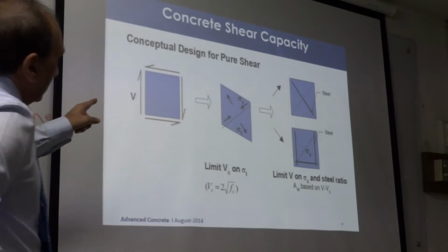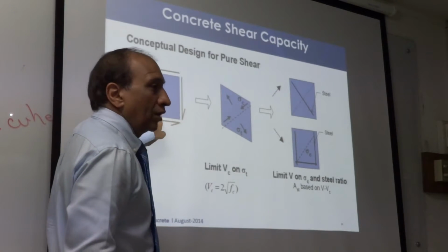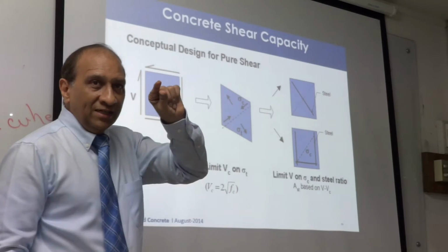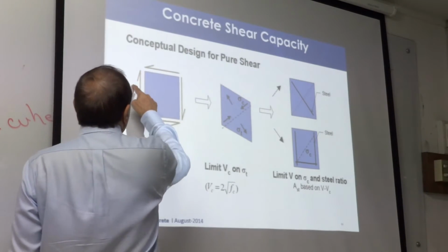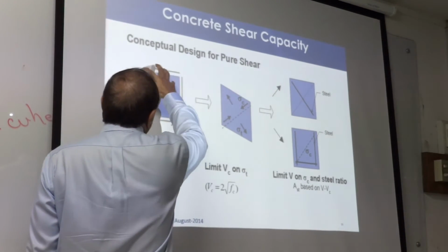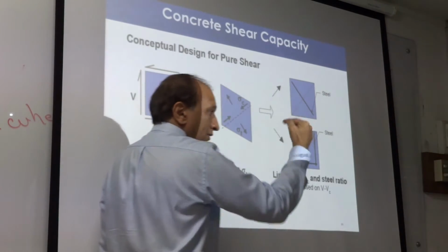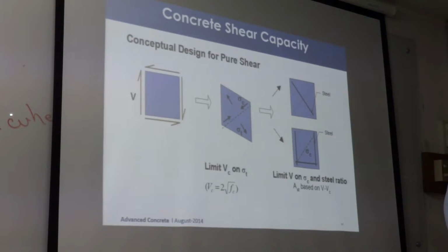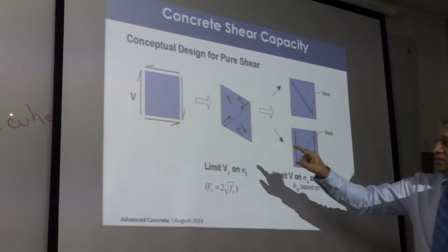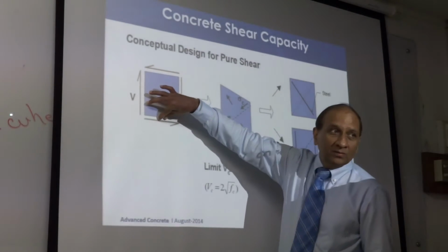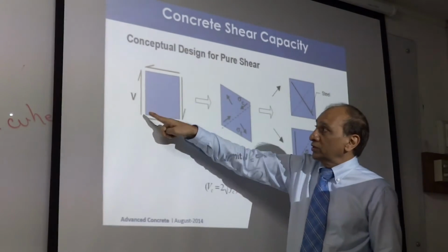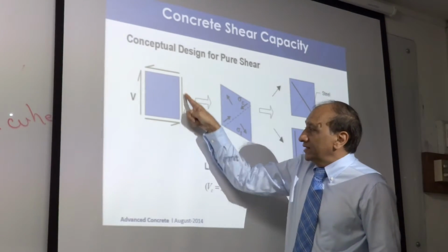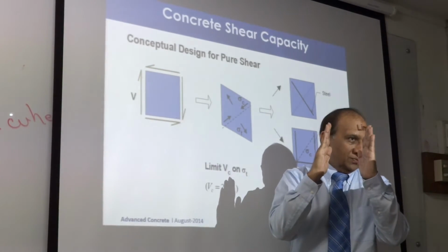Now, let's take one of those points on that section, on the beam that I showed you. One element on that section, and you will see that this is a shear. So shear must always be like this, on one element on the side of the beam, not on the section, but side of the beam, on the very small slice that we talked about. This width is very small, nearly 0 at the section. So the stresses exist like this, and shear stresses, this one and this one on the two sides you just saw, right?